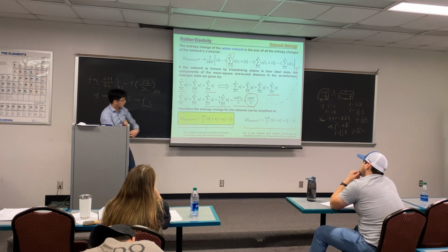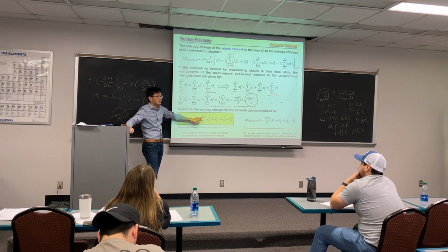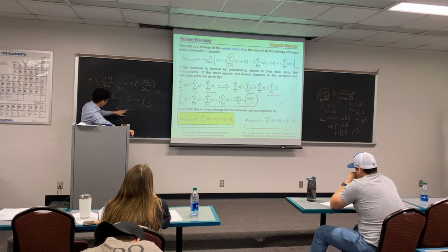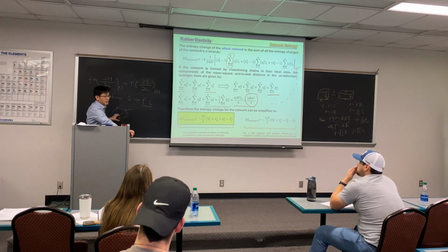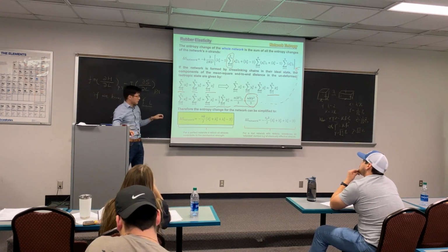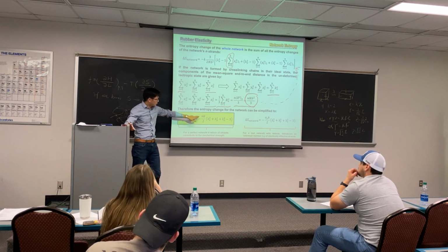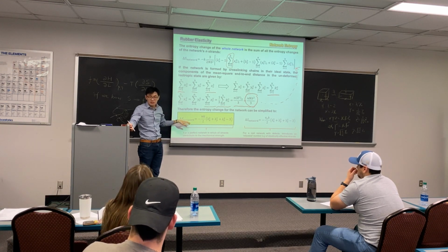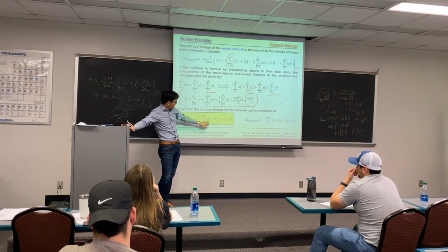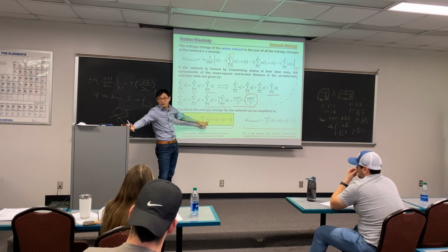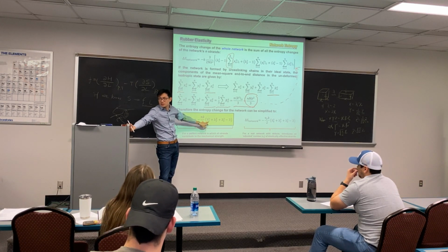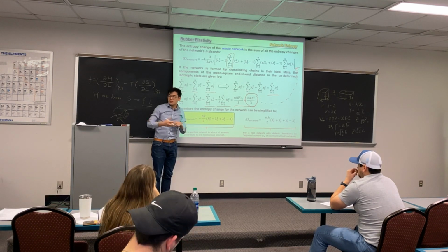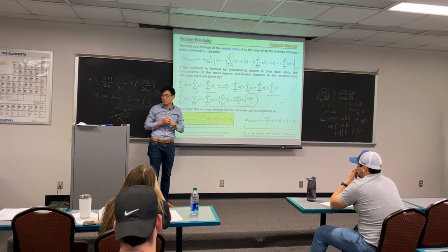N is a constant, okay? If your network is defined, you know how many strands it has. So if you look at this box, you can count 1, 2, 3, 4, 5, 6, 7, 8. There are 8 polymer strands inside the system. This will be a constant. K is constant, so the change in delta S in the network is inversely proportional to the draw ratio inside the system, squared. So if you pull it twice or 3 times,